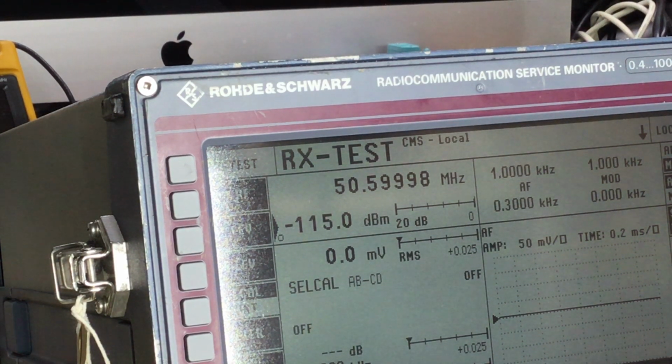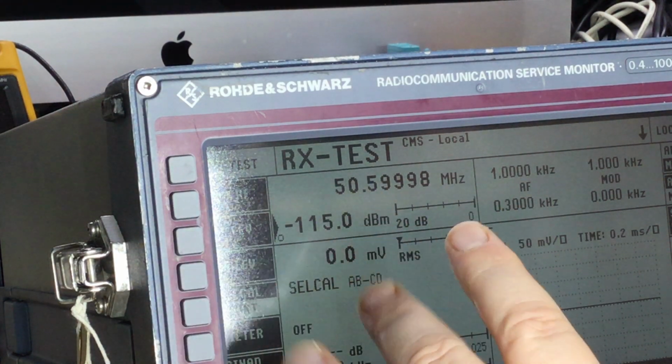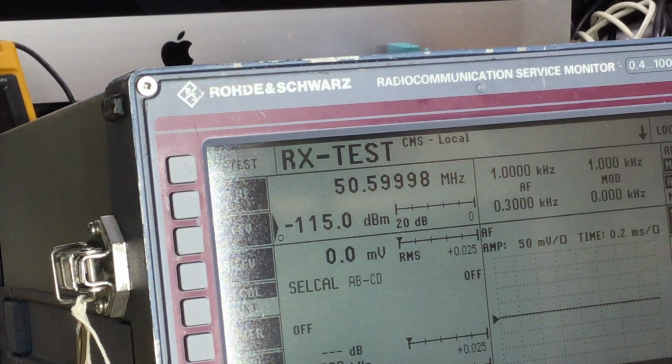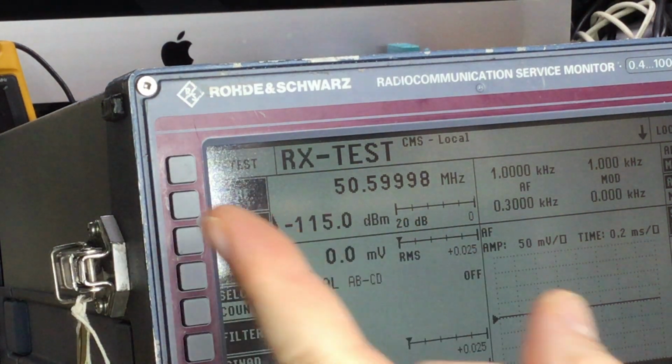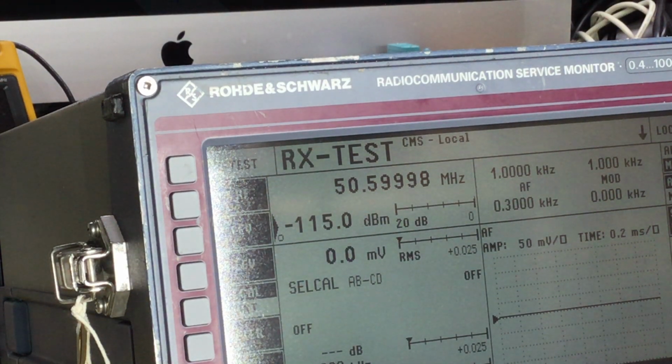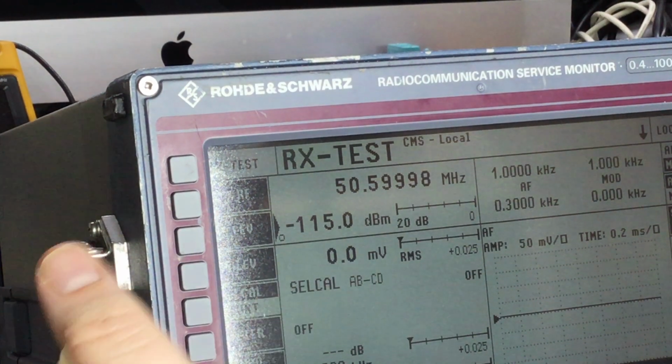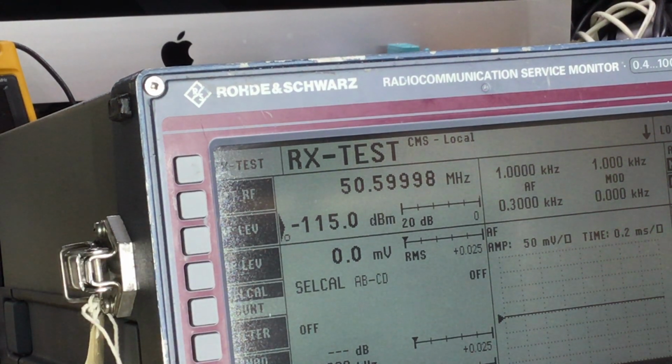I've noticed as well the display is behaving itself. The backlight would normally be flickering when it starts this problem, so it could be that moving it off the bench up there down onto the service bench has disturbed it and sorted it out, which, knowing my luck, is probably what happens. If I tap it I'm not getting any changes at the moment, so I'll have to wait till it starts playing up and then come back in the video to show that.